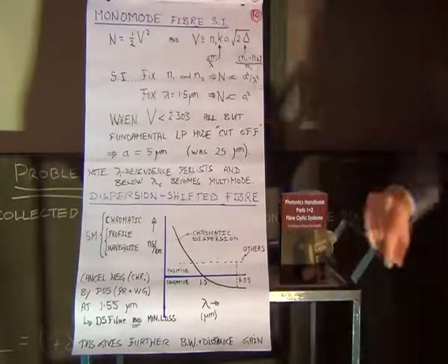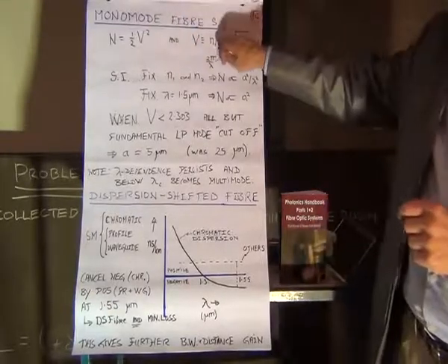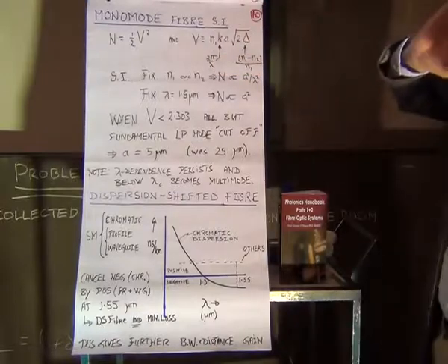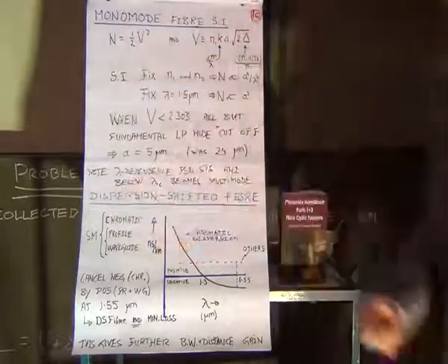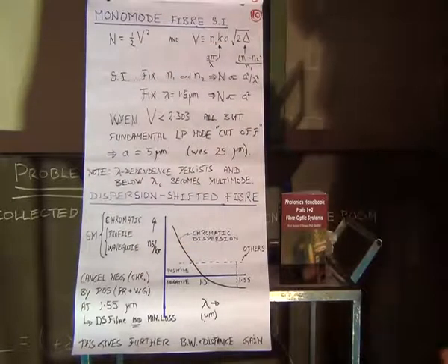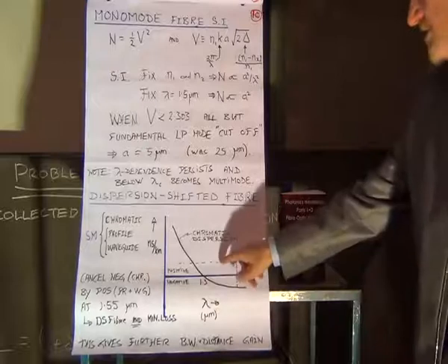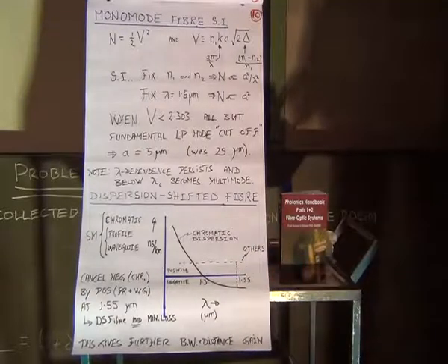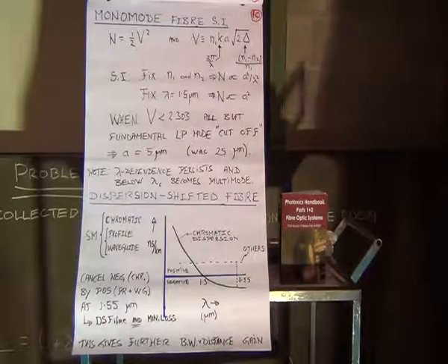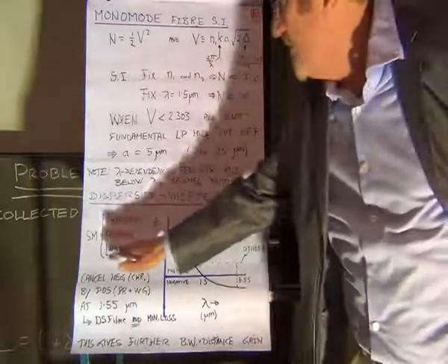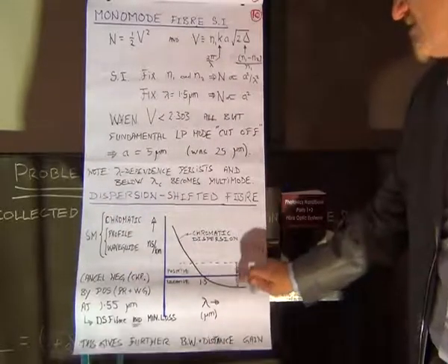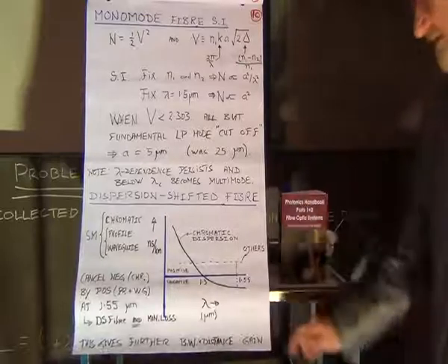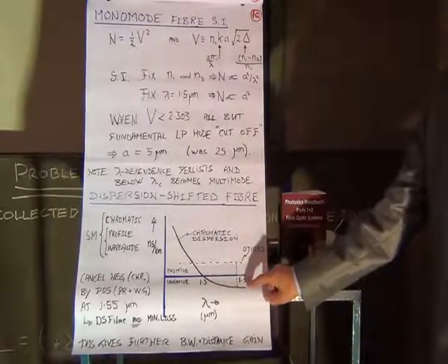We're using monomode and we're using step index at this stage. And modal dispersion is gone. What remains are these three. Something occurs to us. Chromatic is negative, but the other two are positive. Can we trade one off against the other and get zero? And that's what we do. We trade them off, we adjust the waveguide and profile somewhat, okay, so that it exactly cancels chromatic dispersion, and that happens exactly at 1.55 microns.